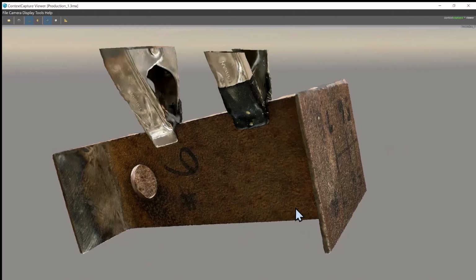So that's another situation where the quality and the precision of what we're seeing has been proving very valuable. As I mentioned, we're not necessarily to the level yet where we can measure steel section loss in the same capacity we would with a D meter or something like that. However, we are able to get close, right? And we're able to start using it with emerging technology, the size of photo sensors, LiDAR, things like that. It's only a matter of time before you can measure crack widths and steel section loss and things like that.